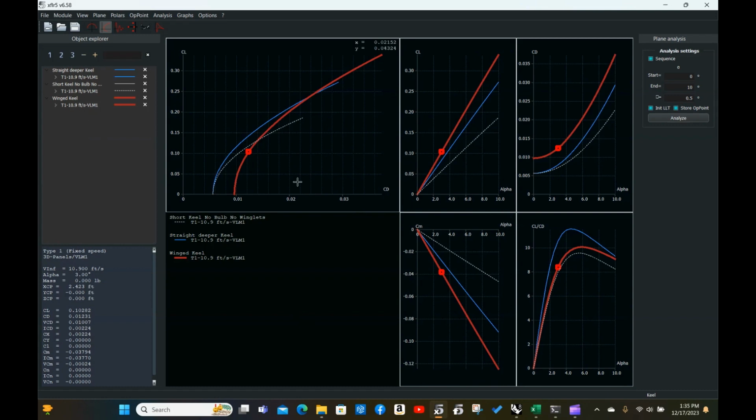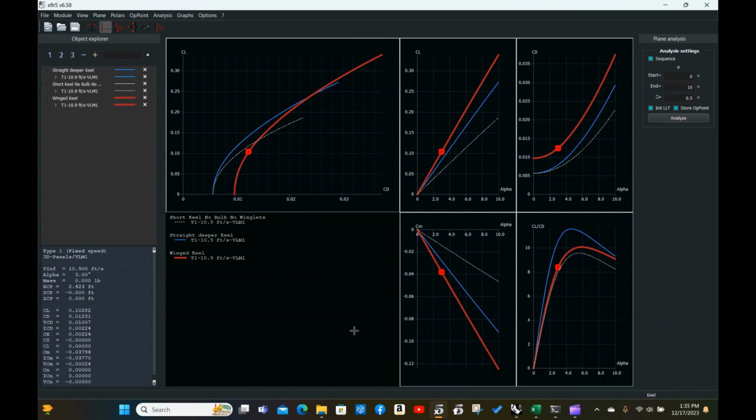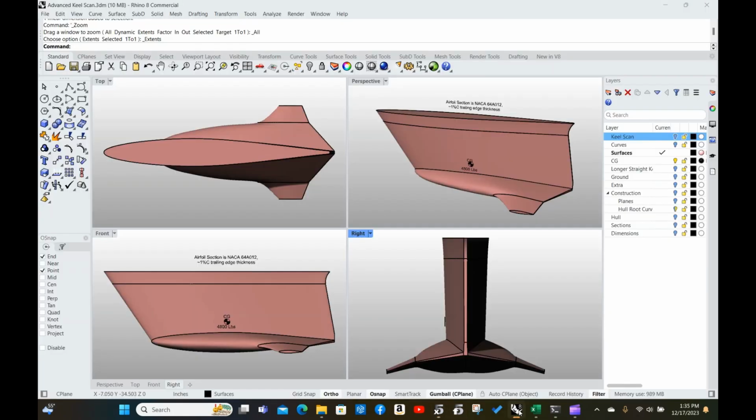So the keel is producing more drag, but the hull will be producing less. Combine that with the fact that the Hunter has a very efficient rudder, and it depends on whether you're using the rudder to counteract some of the weather helm, producing a little more efficient side slip resistance. So in conclusion, I would think that what we're talking about is very, very minor.